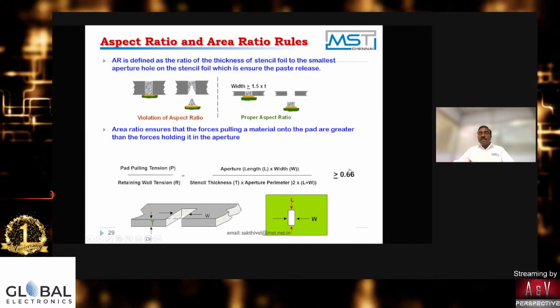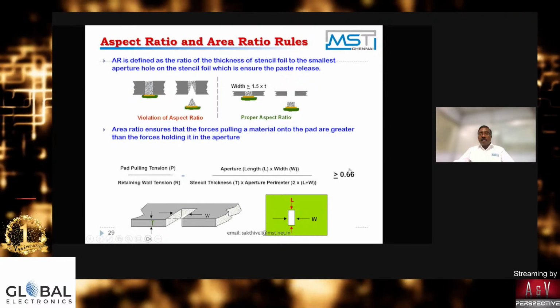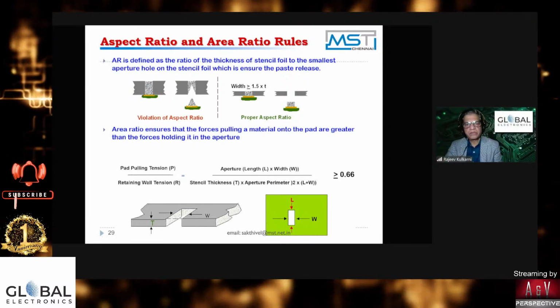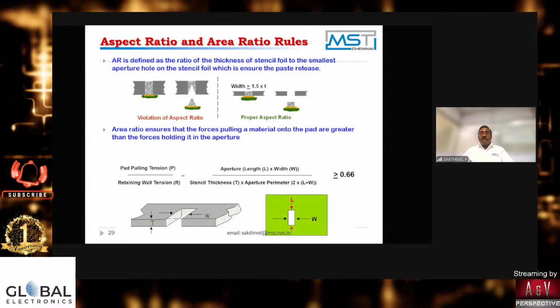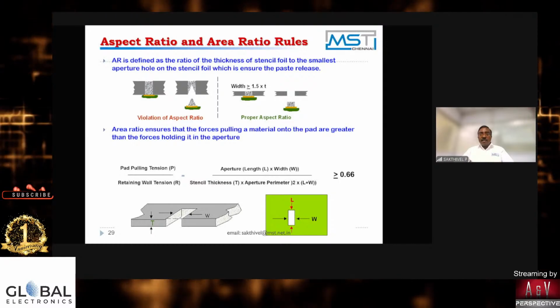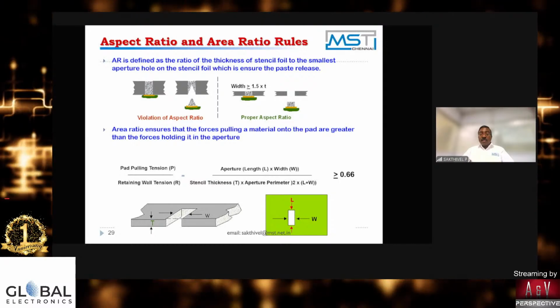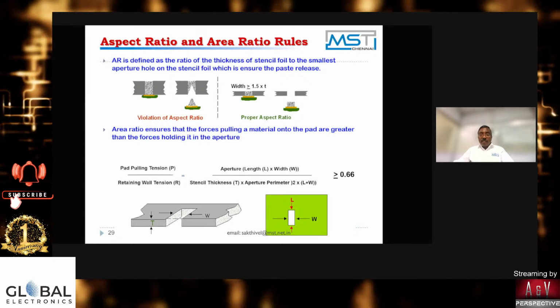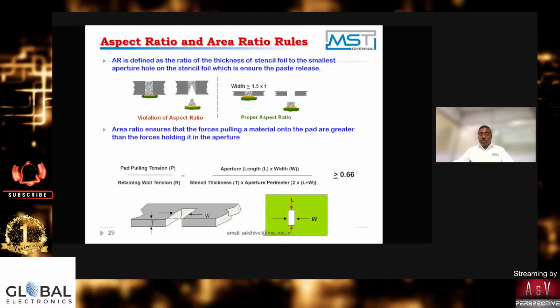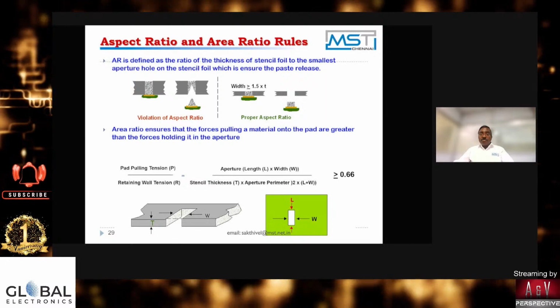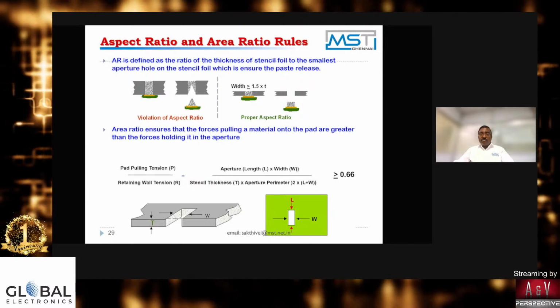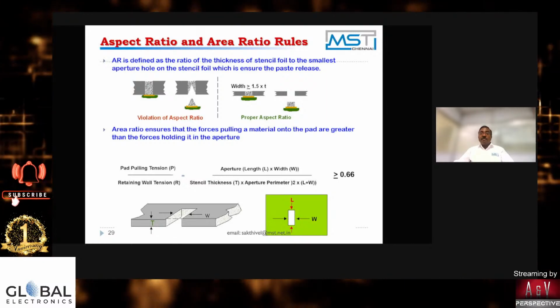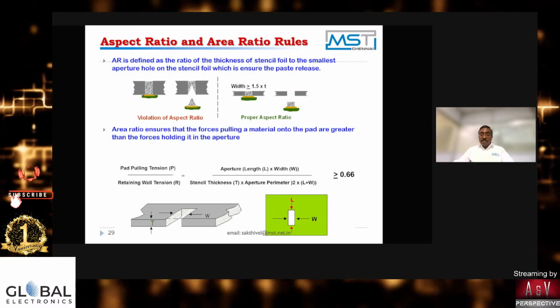That is the general guideline. It is not fitting any of the recent components. So in recent days, I've been doing a 0.5 area ratio, and we have still been successful because we've been adopting a different deburring method.